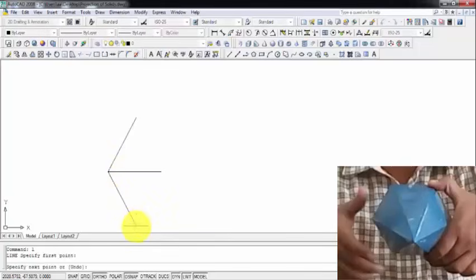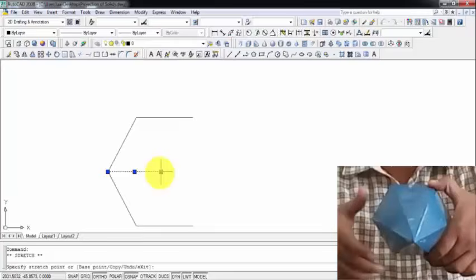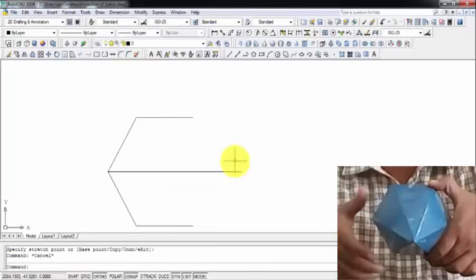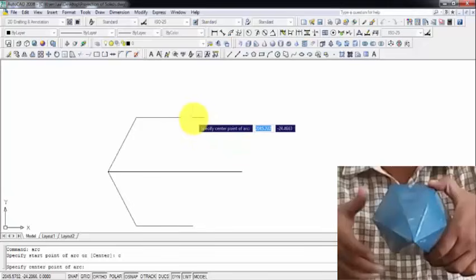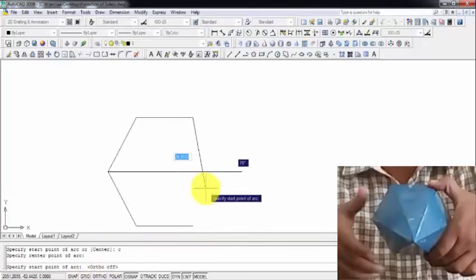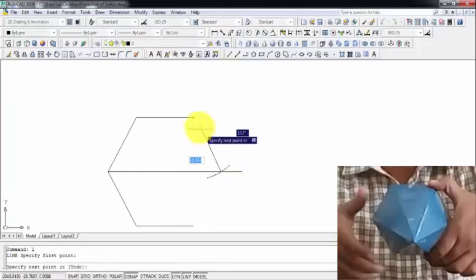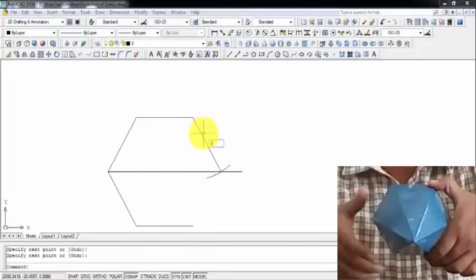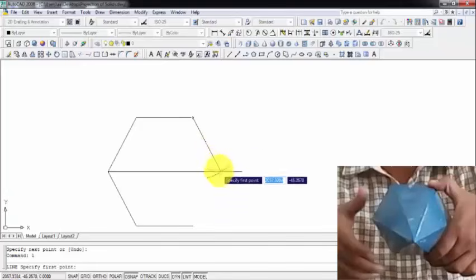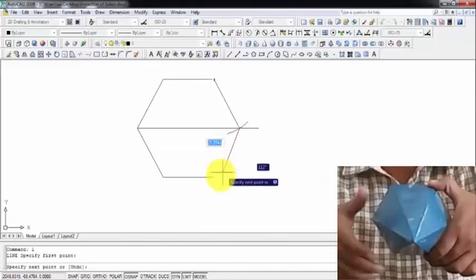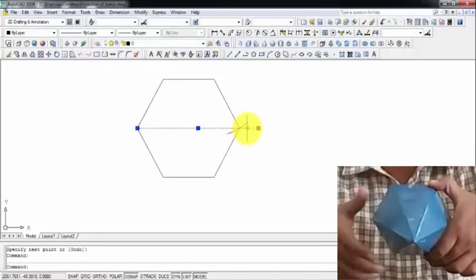So the next step is to go 25 millimeters straight. Then from this point we're going to go 25 millimeters straight. Alright, the best thing to do right now is to extend this line, and with this point as the center, we're going to put up an arc of 25 millimeters. I'm going to show you how that can be done. So this is how you need to put up an arc. Now this intersection point will give you this. And then join this one with this over here. Let me make it very precise.